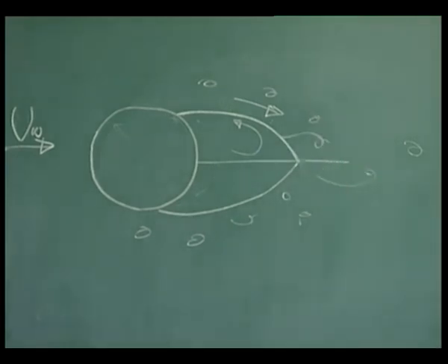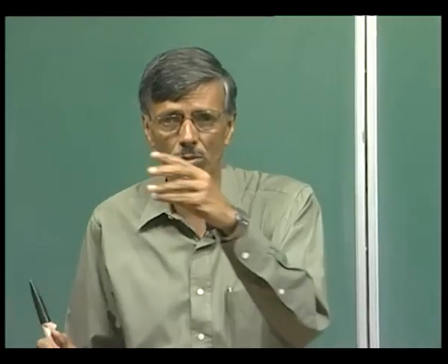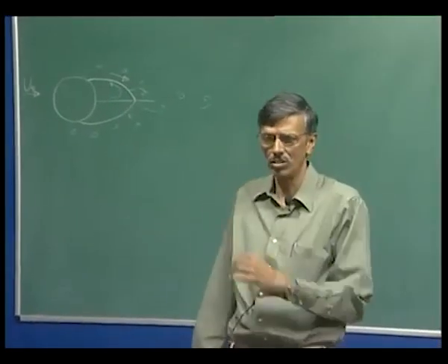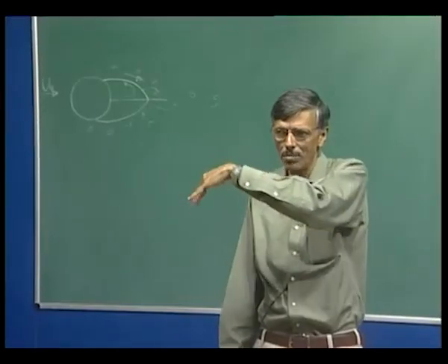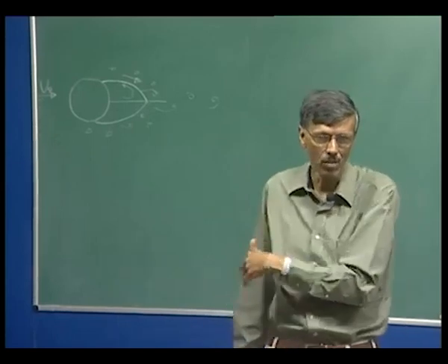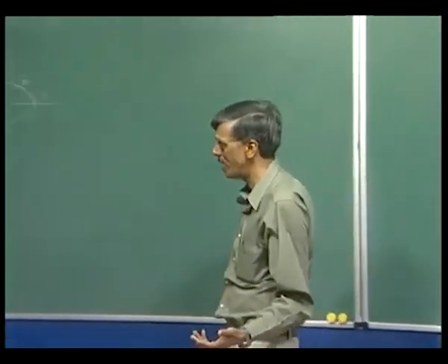Okay. Now, if you go back and look at those results, those were shown in Fritz Homann's case, something that I would like you to take a look at. There you would see that even the results produced for 65, you would have seen that this is more of this kind. You have an attached bubble at the end, and the end of the bubble is fluctuating and creating an undulating wake. So, this is not what we would say in the classical sense, the Karman vortex shedding.